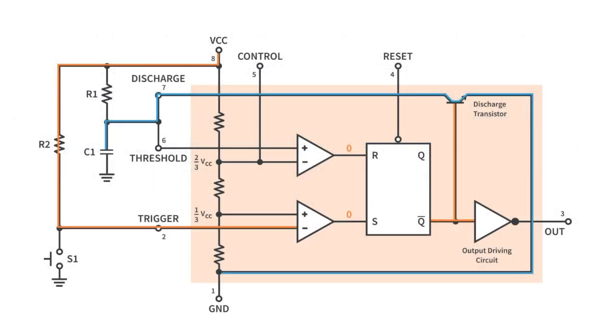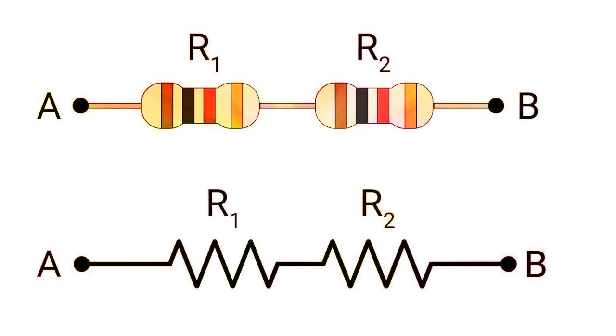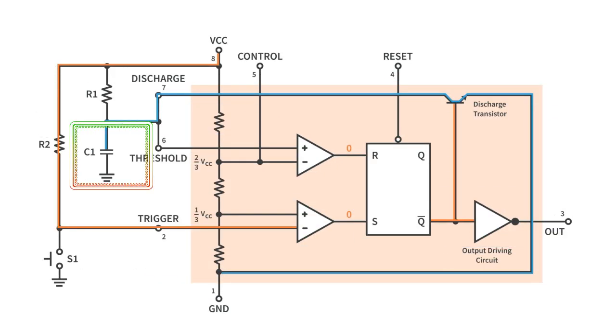If this time difference of 17 milliseconds, 500 to 517 milliseconds, is unacceptable, then instead of one single timing resistor, two different value resistors could be connected together in series to adjust the pulse width to the exact desired value, or a different timing capacitor value chosen.